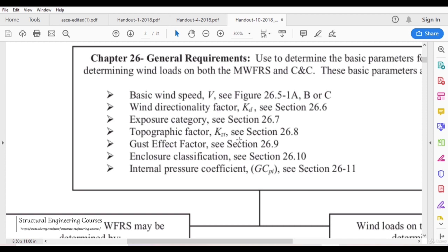It puts a pressure for, let us say, 3 seconds in the American standard. So the peak pressure remains there for 3 seconds and then it comes down, and after some time it again reaches the peak pressure of, let us say, 1.5 kilonewton per meter square, and then goes down. So the gust effect factor depends upon the rigidity of the building.